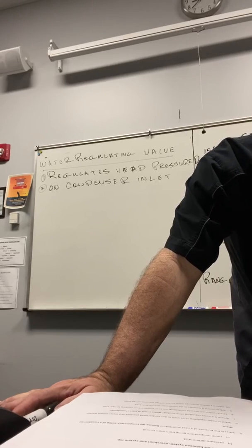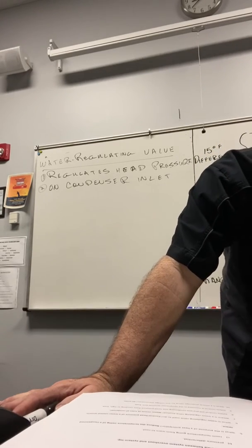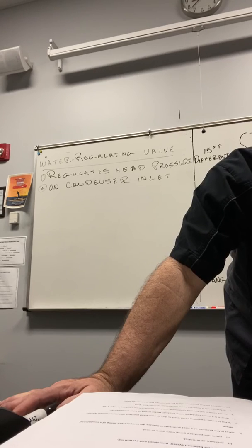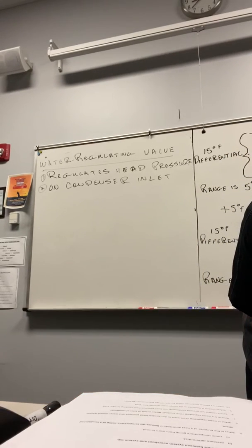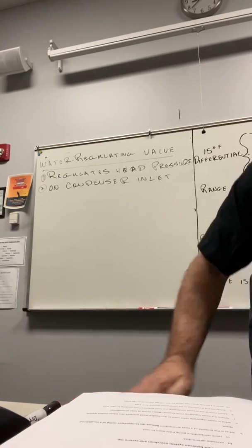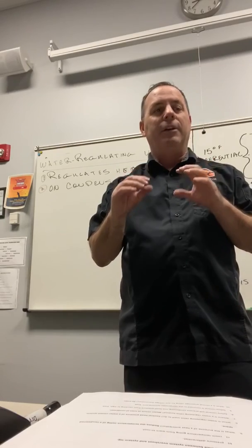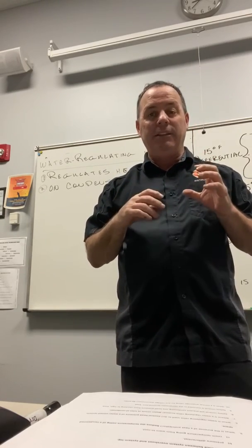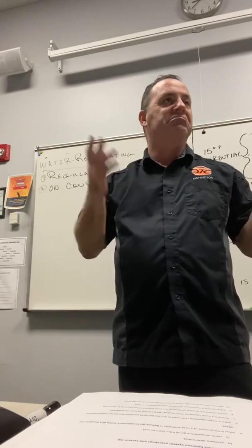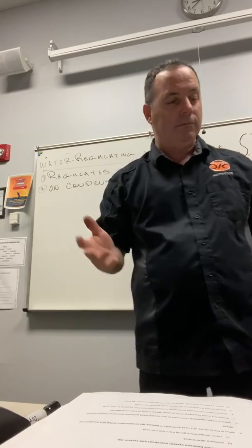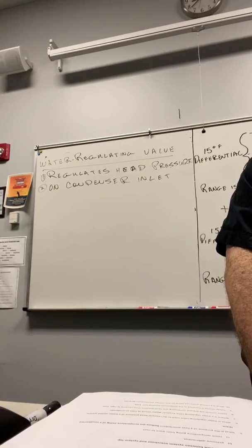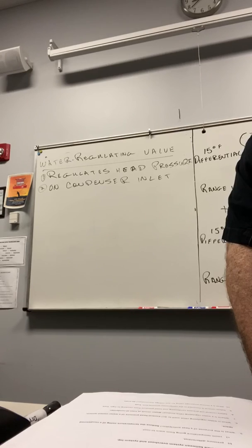Okay, now the last thing we got right here is gas pressure regulators. What do they do? These are used in all gas systems to reduce gas transmission pressure to a usable pressure at the burner. So a gas pressure regulator regulates the amount of gas coming in, going to the gas valve inside the gas furnace. It says the pressure for natural gas is usually 5, and the burners could be manufactured to burn at 3.5 water column. Any questions about that?